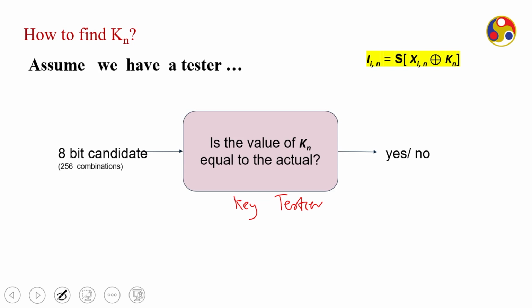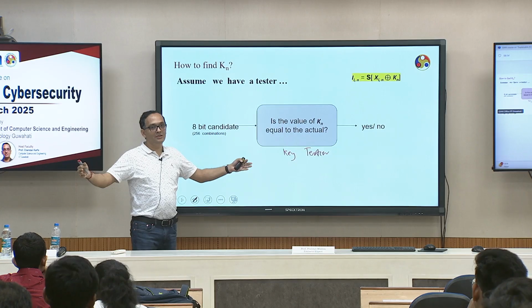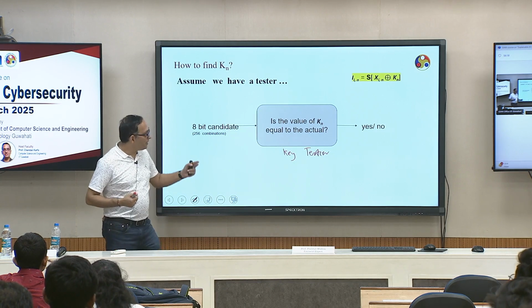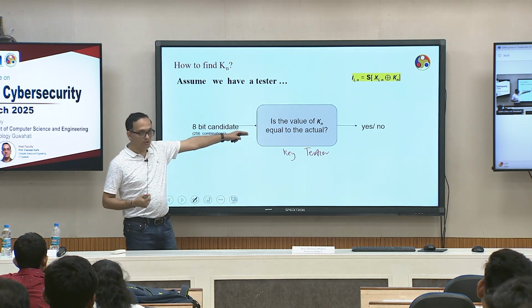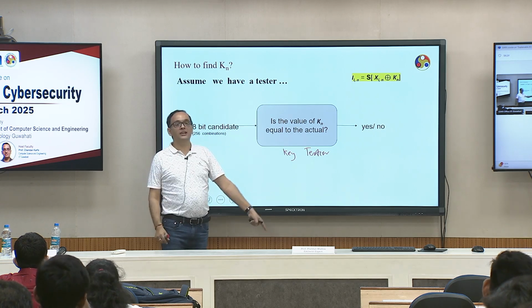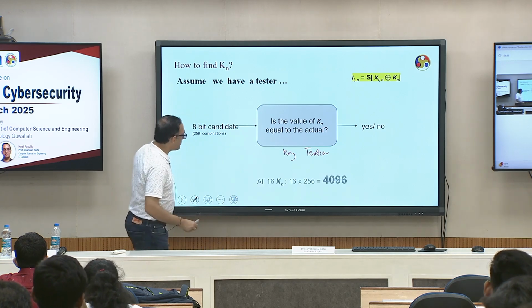And you remember, I just told that if this is the correct key, what will happen? If you give that LSB 0 and LSB 1, that should give you two different power patterns, right. So that is the kind of differentiator. So if your key value can give you that differentiator, then I can say that this is the correct key, right. So how many combinations will you have?